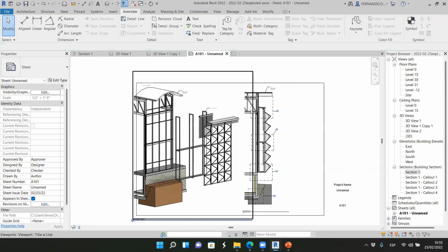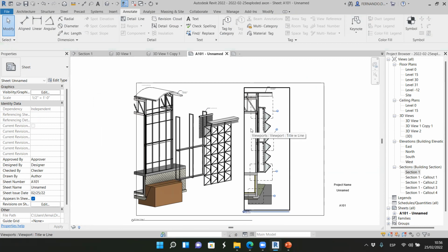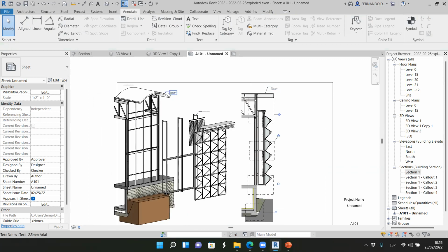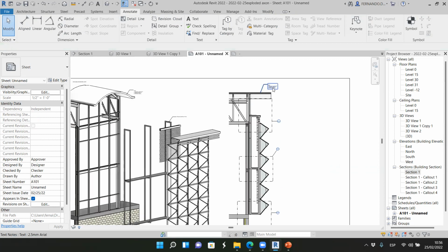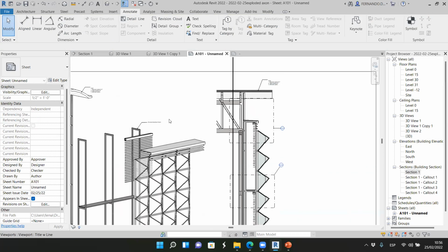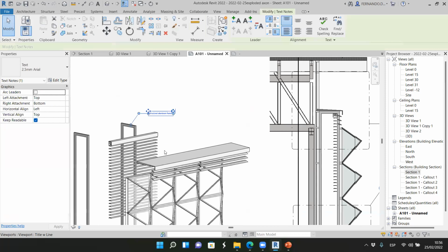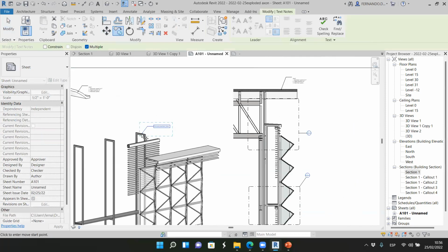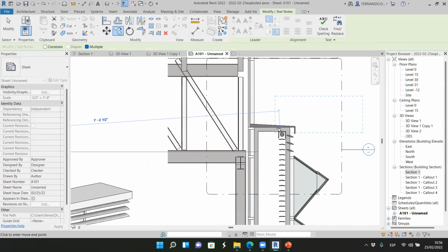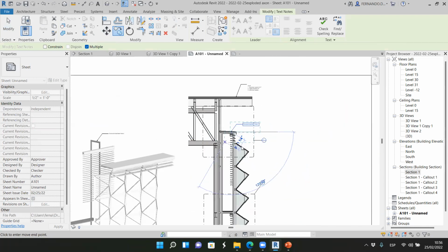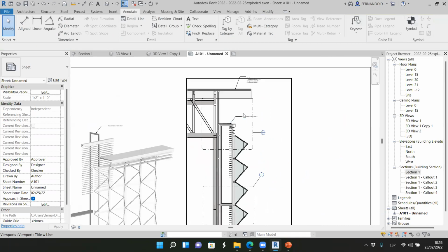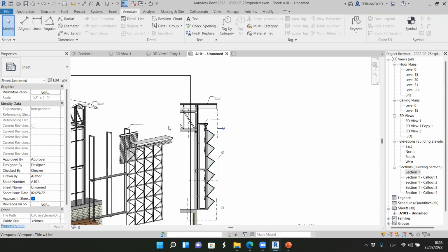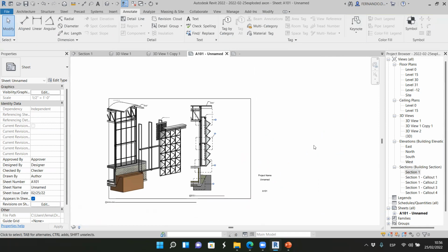If we are showing the same thing in two different views, the exploded axonometric view and this, if we have the same element, we have to define the same element twice. It's not an excuse that it's defined here. No, we have to define it every time. So if this is the structural aluminum frame, make sure that we copy. And here we have the structural aluminum frame. Okay, so make sure that we are always defining the same elements here and there, in both drawings.